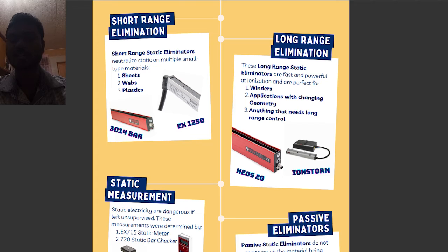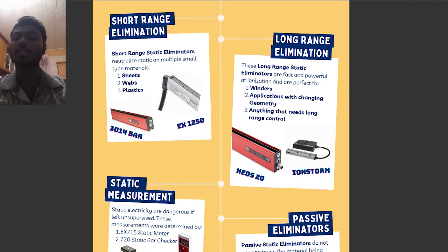This is dust and static. According to dust and static, statically attracted dust must be removed as soon as possible after extraction. If the dusty moldings are stored for a few days, the electrostatic attraction can be replaced by molecular bonding.